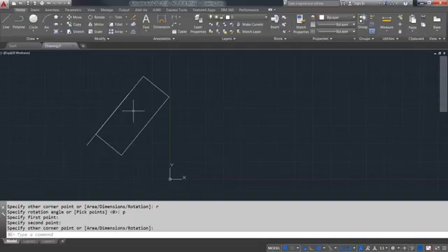And just a few more left here. Let's see if we can't finish up. We got, why does 2016 DWG to PDF PC3 randomly black out my blocks I have a wipeout background on? That sounds like a good troubleshooting question. You may want to post that on a forum or send us in a support case if you have support with us. But from my recollection, that sounds like a CTB or possibly a layer issue. You might want to check with support on that.